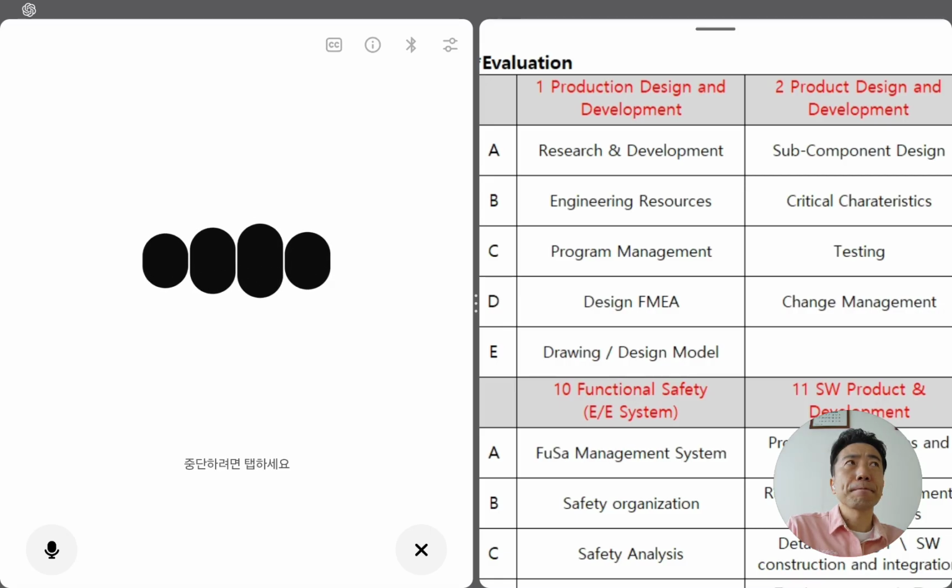3. Can you explain how you identify obsolete drawings and prevent them from being used in production? Answer: Obsolete drawings are clearly marked as void in our system. They cannot be downloaded or printed for production use. We also remove physical copies from the shop floor and replace them with the latest approved version.